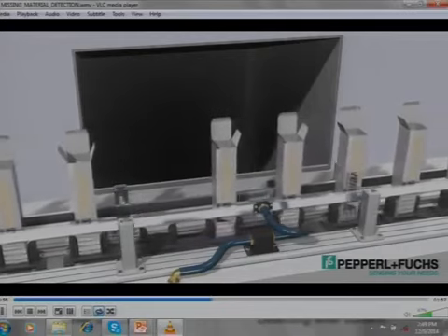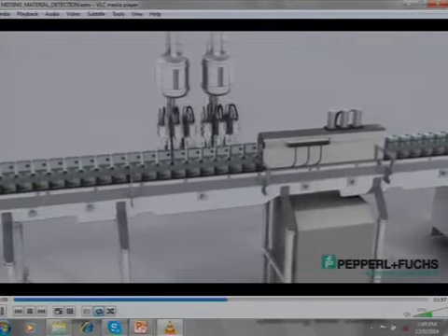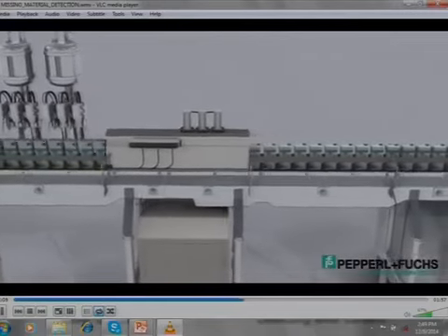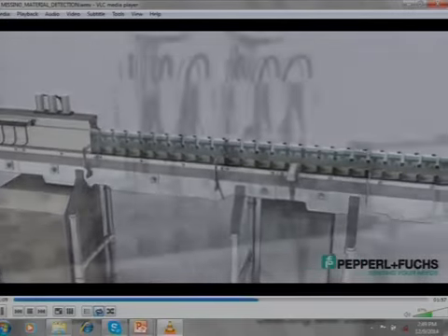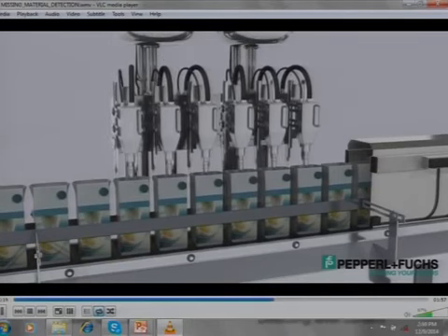You would see that there is a pneumatic cylinder. As soon as the sensor receiver, the positioning system, says the target is there, the ultrasonic sensor gives an output which is a non-conforming output. The pneumatic cylinder is made to actuate, and it will eject that pouch out of the line.